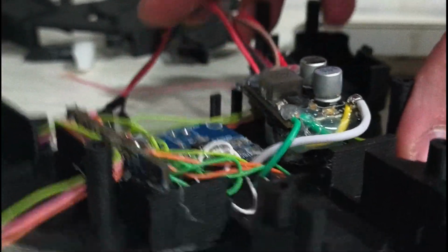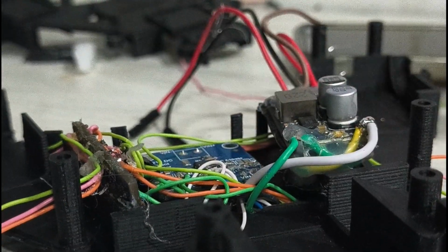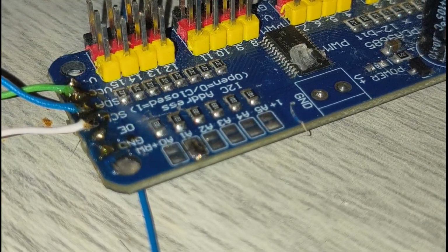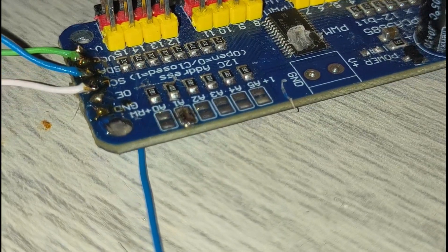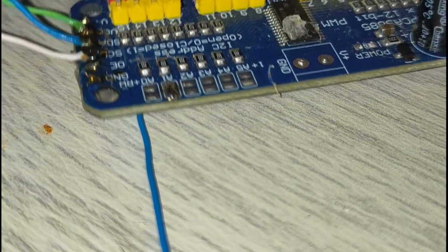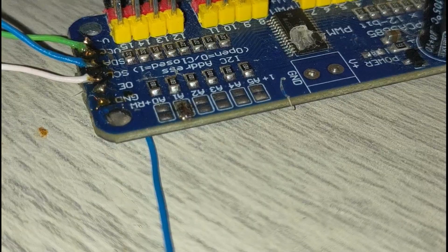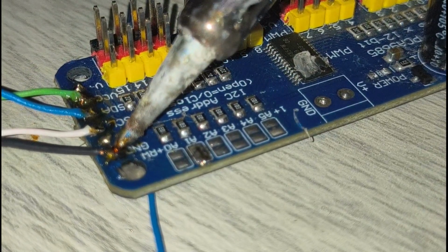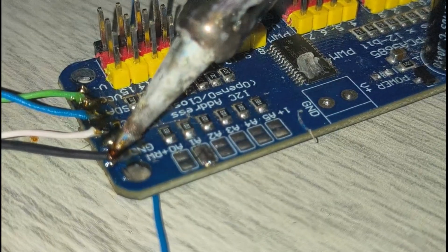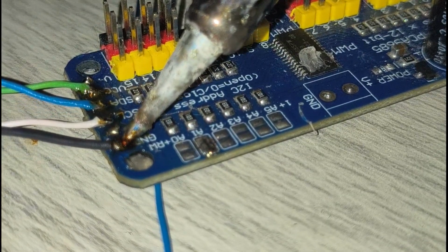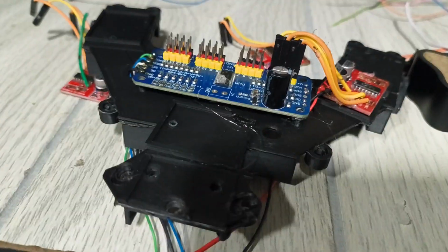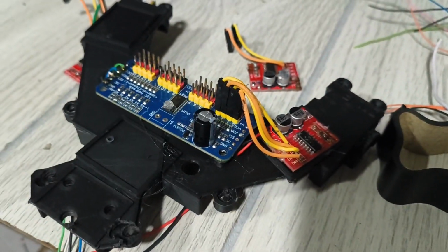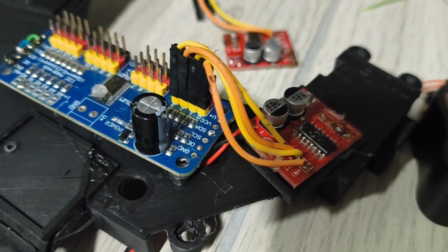Now it's time to turn your attention to the front of the robot, where you'll have to route the 5-volt connection from the secondary 5-volt board to this PCA board right here. You'll also have to remove the pins on it so you can solder the wires directly to it, which is a common theme here. So you start out with a normal I2C connection, but then you tie the grounds together and add a 5-volt connection to the V+ pin, and that should allow you to use those red and black pins to power extra 5-volt accessories off the secondary 5-volt lane.